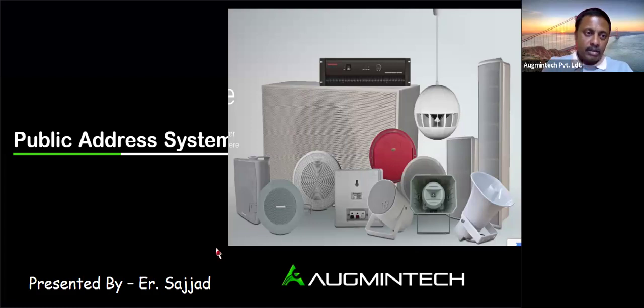So that the speaker, somebody live or some recorded messages, would be exactly instructing only those occupants to move out of the building, maybe through a stairwell pressurization system or a fire exit, so that evacuation is easy. That's what we call a phased evacuation system. For that purpose also we are using the speakers nowadays, right? We call it a voice evacuation system, usually the same speaker system, but we are interconnecting it with the fire alarm system also.